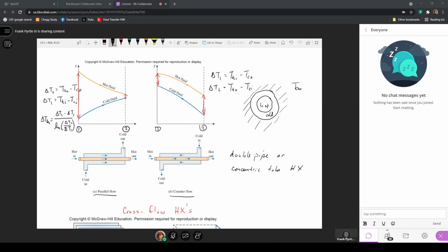So here, this counterflow heat exchanger, again, is going to give you expressions of the greatest average temperature difference that occurs along the length of the heat exchanger, since there are just two considerations for a double pipe heat exchanger. For the same inlet and outlet temperatures for the hot and the cold fluids, you'll get a higher average temperature difference for the counterflow heat exchanger when comparing the counterflow and the parallel flow heat exchangers.